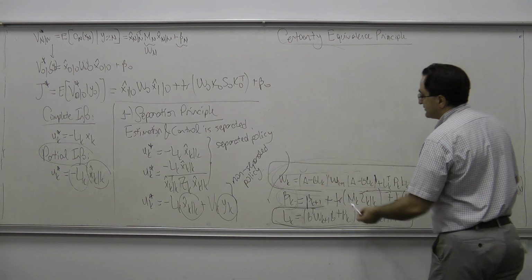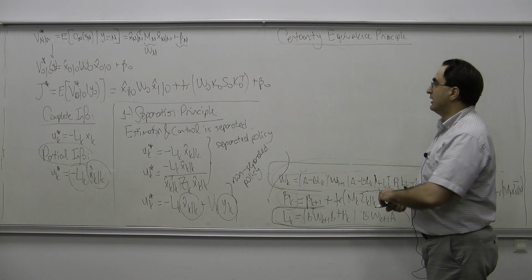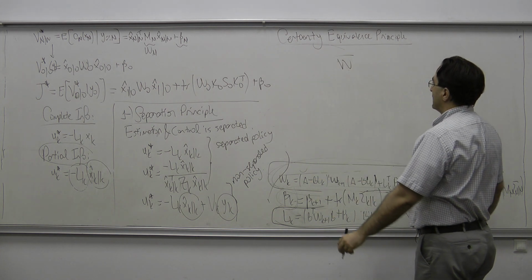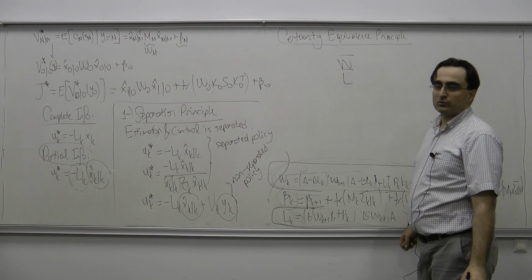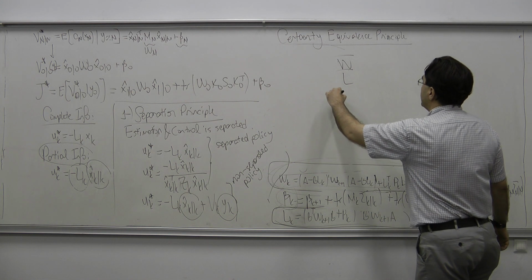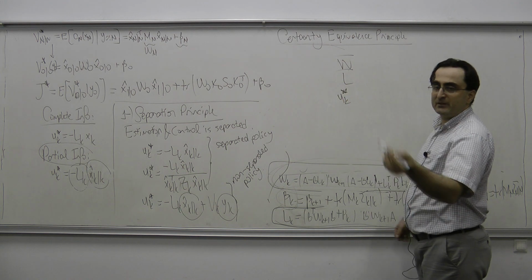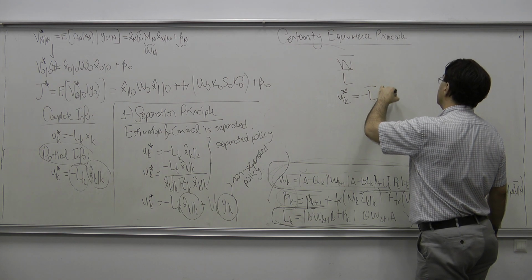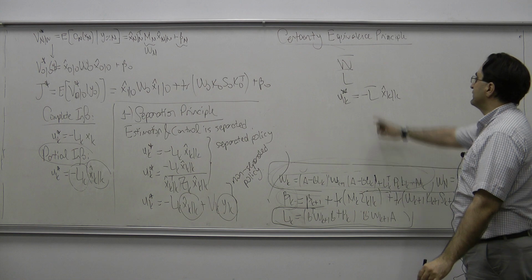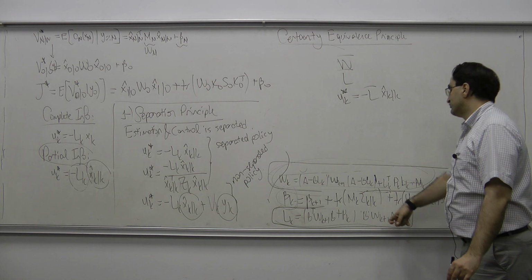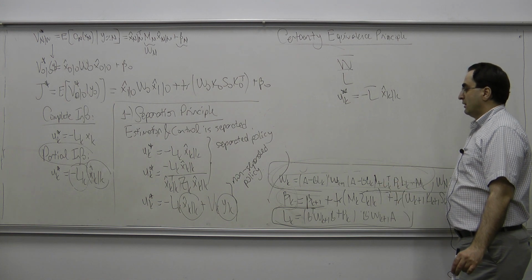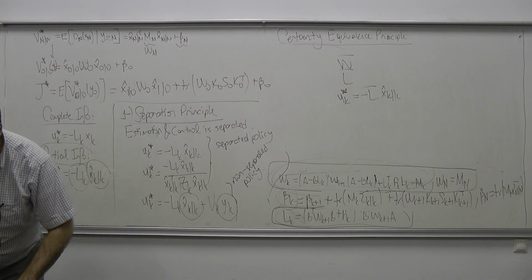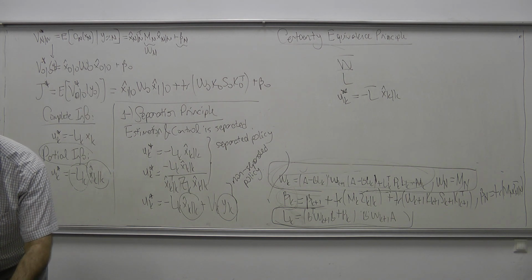So you can let the horizon n go to infinity, and calculate the steady state W bar and steady state control gain L bar, and then your steady state controller in the infinite horizon case would be minus L bar times x at k given k. Okay? And this L bar and W bar can be found in the same way as in the complete information case. Okay?